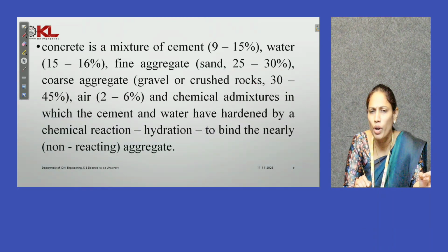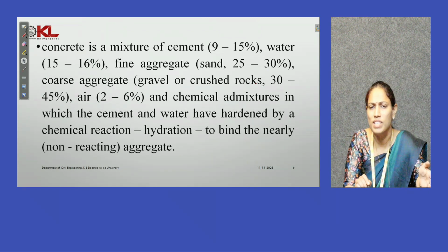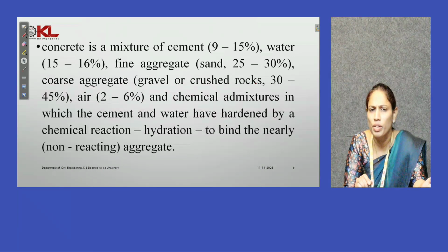Why are we considering air? This is nothing but a void which is formed inside the concrete, and those voids cannot be avoided as of now. Up to 6% we can consider that air is there in the concrete. Beyond that 6% we should avoid air penetrating into the concrete, so that the strength of the concrete which we have designed will be maintained throughout the design period.